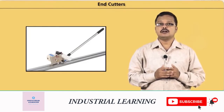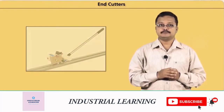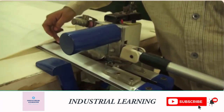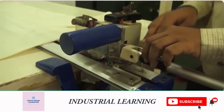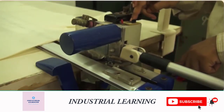End cutters are used to cut the end of the fabric after each spread while spreading. This is an end cutter generally used in the spreading process. The end cutter has a rail upon which the entire machine is housed. This is the round knife, this is the handle, this is the on off switch, and here is the ply counter.